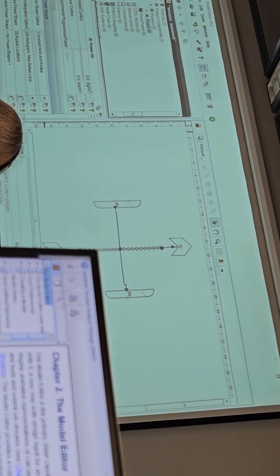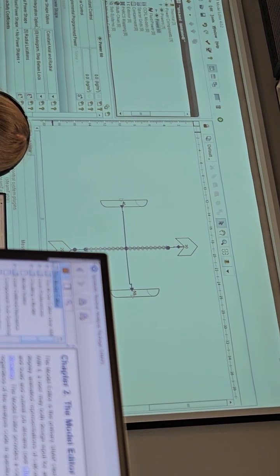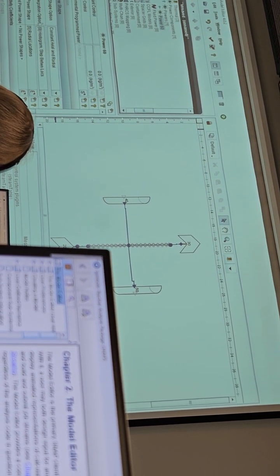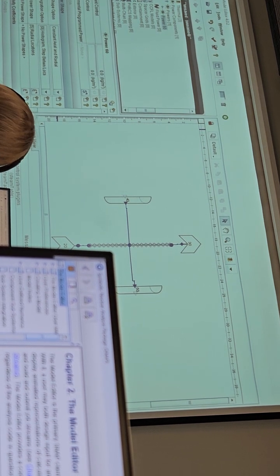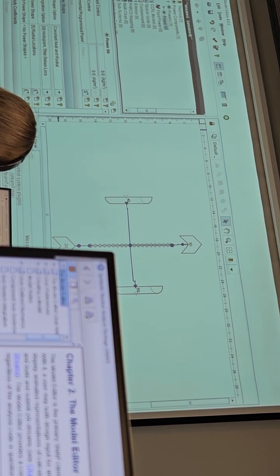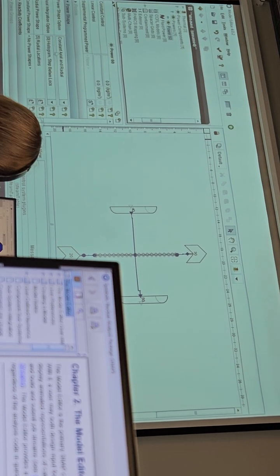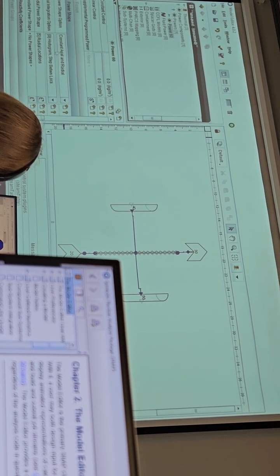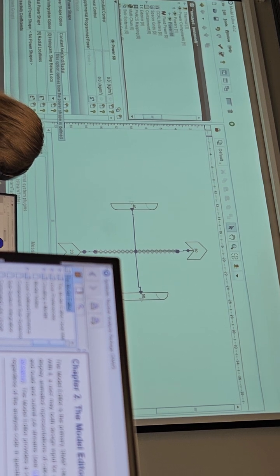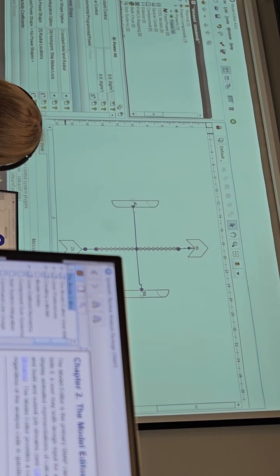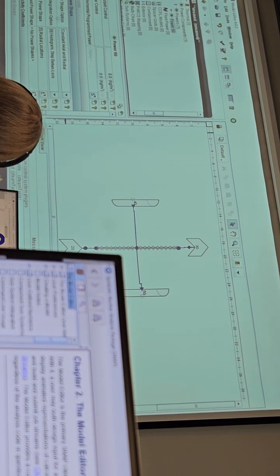For our case, as you remember, we have unheated surfaces, an unheated fraction of the heat structure. So then we need to define the power shape option as a constant axial and radial. In both directions, the power will be supplied to the heat structure uniformly along the whole volume.